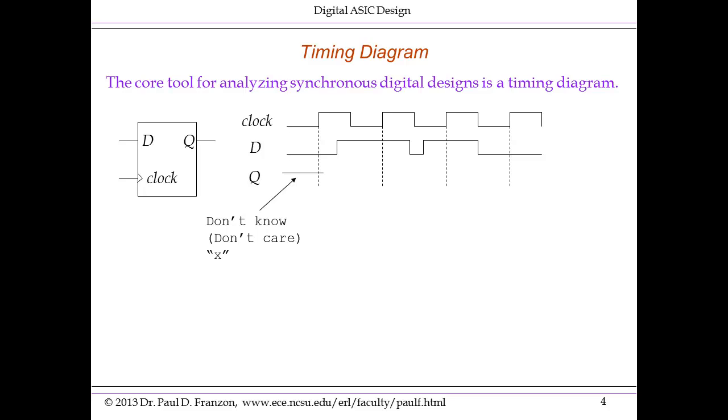On the first rising edge of the clock, Q becomes D after that rising edge, so Q becomes 0 a short period of time after the rising edge of the clock. Here I've drawn it with a slight delay, as would happen in the actual logic from the clock edge. In RTL, it will actually be falling on the clock edge. On the next rising edge of the clock, D is resampled. At this point it's 1, so Q becomes 1 after the rising edge.